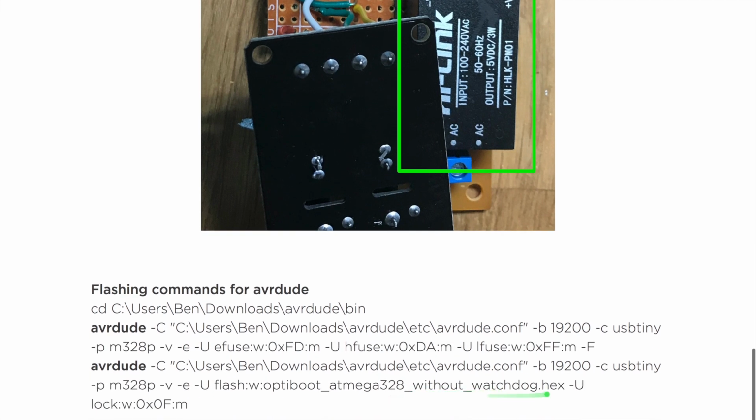Now my bootloader is built without a watchdog. A watchdog is a trick they did over there to reset the microcontroller every couple of seconds, just so you will be in bootloader state and try to program itself remotely. I'm going to get the packets from the RF24 and flash the sketch. But I didn't want my station to restart all the time, because I wanted to be ready to get commands from my server, my home automation server.